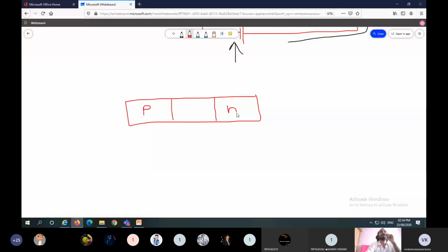In order to allow a very large amount of current, the N layer is highly doped. And to block very high voltage in reverse bias condition, an N minus layer is introduced in between the P layer and N layer. That is the difference between a normal diode and a power diode.